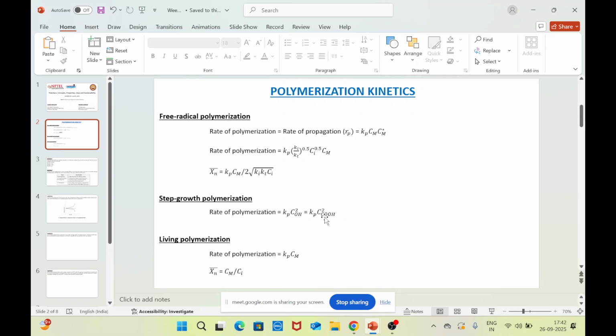These micelles are the centers for the polymerization reaction, or you can say these micelles act like reactors for the polymerization, just like the droplets do for suspension polymerization. Gas phase polymerization typically happens in a heterogeneous phase. Here, depending upon the heat produced during the polymerization process, the reaction kinetics will vary.